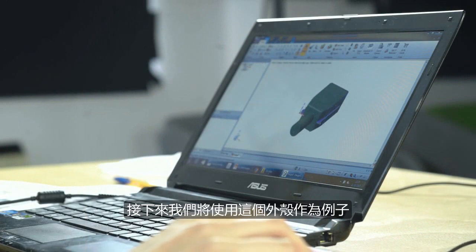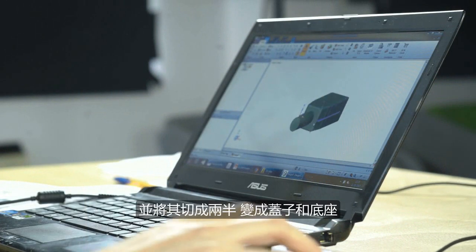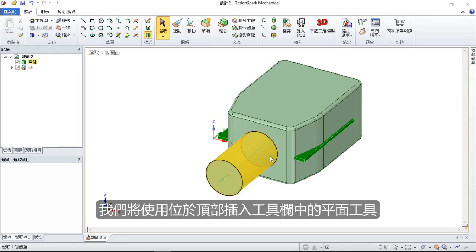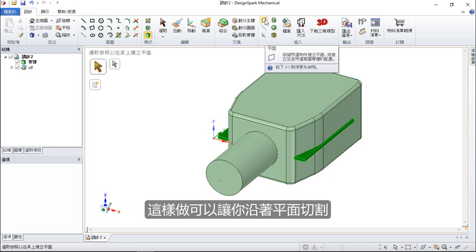Next we are going to take our enclosure and actually cut it in half so that you can have a lid and a base. To do this we are going to use the plane tool, which is located in the insert toolbar at the top. And what this does is allows you to cut along the plane.